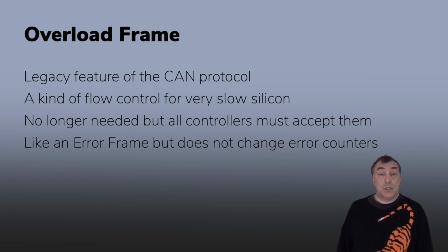This lets us freeze all the controllers on the bus in a loop by sending one overload frame after another. When we stop, the controllers will unfreeze and continue as if nothing has happened. Let's go to the lab and see a freeze doom loop attack for real.